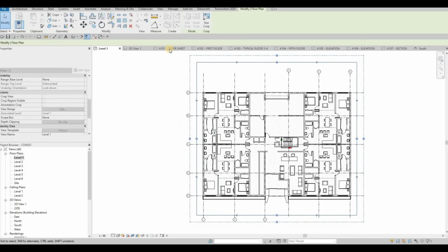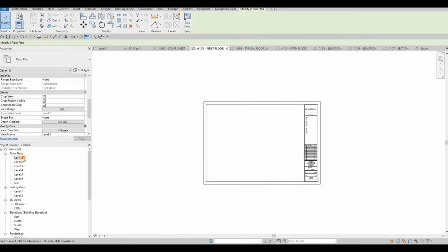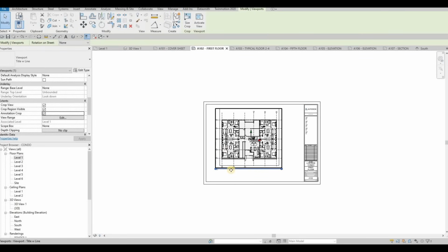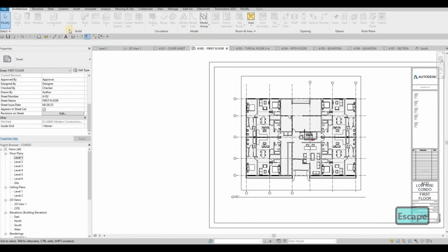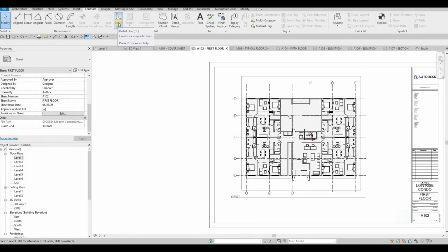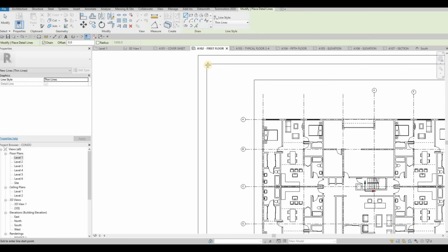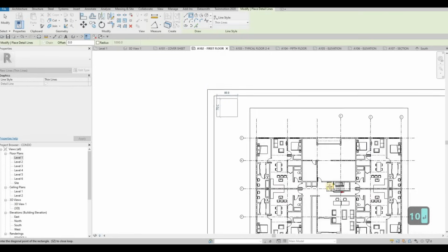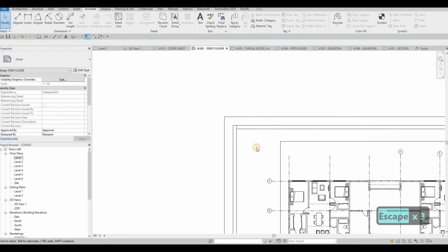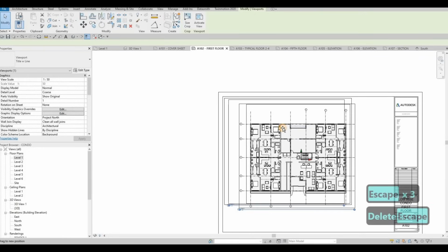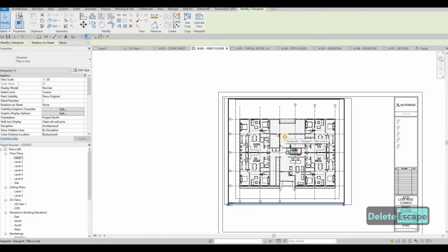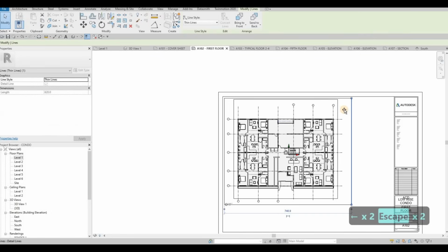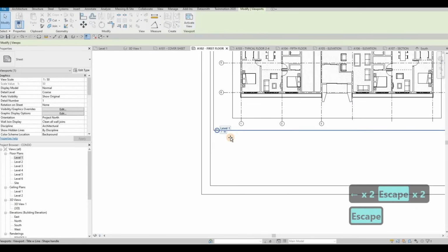So now what we're going to do is go back here and then drag and drop here. So as you can see, everything looks nice. I usually, in our company, we add border lines. So I'm going to use thin line, and then here we put 10 millimeters and then 10 millimeters, and then we do it like this. Remove this, and then let's add it in the middle where this is, and then we grab this title,